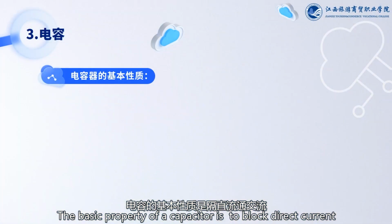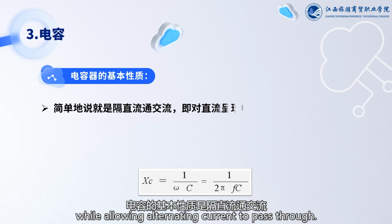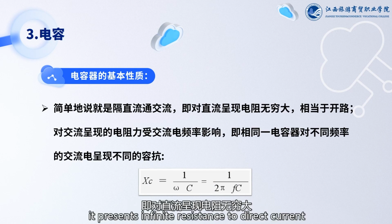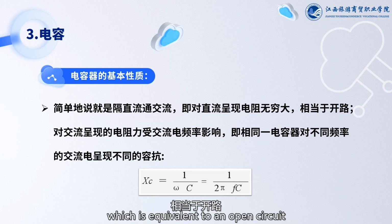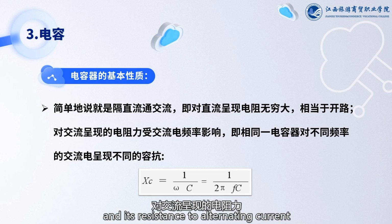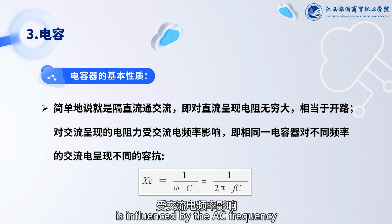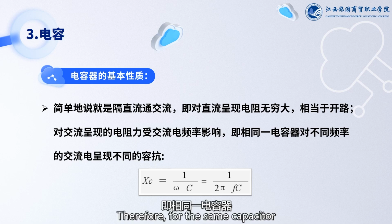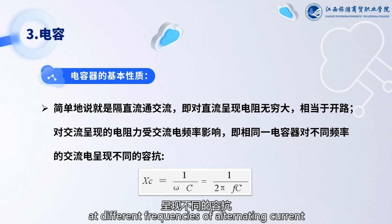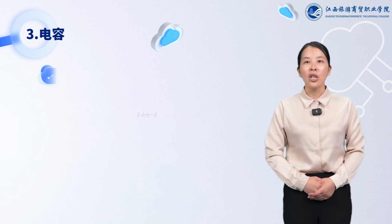The basic property of a capacitor is to block direct current while allowing alternating current to pass through. In other words, it presents infinite resistance to direct current, which is equivalent to an open circuit, and its resistance to alternating current is influenced by the AC frequency. Therefore, for the same capacitor, it exhibits different capacitance and impedance at different frequencies of alternating current.